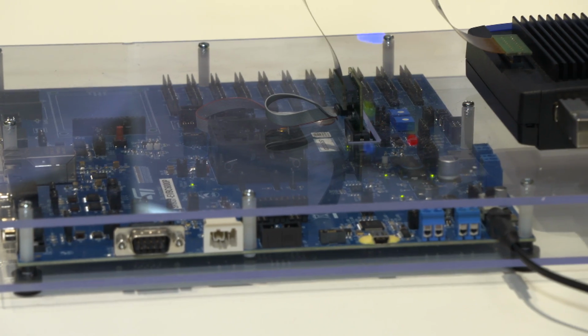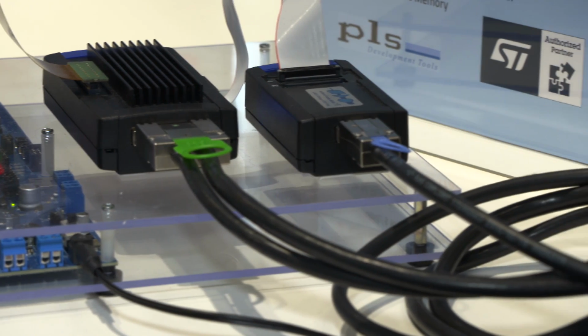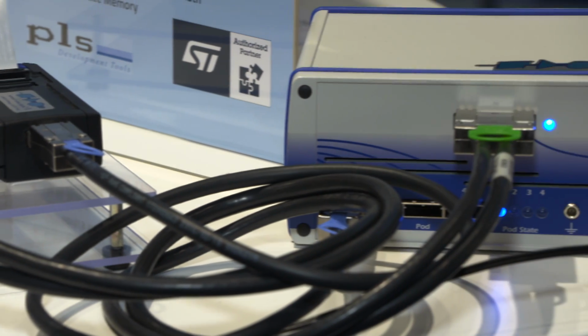And based on this trace information, we can do the measurement of runtime in the tool itself, but we also have the possibility to export the information to other tools. As an example, we have developed a trace based on the ORTI standard for AUTOSAR. So, for example, the Microsar from Vector AUTOSAR system can be traced and the trace information can be exported to the Vector TA tools for deeper timing analysis.